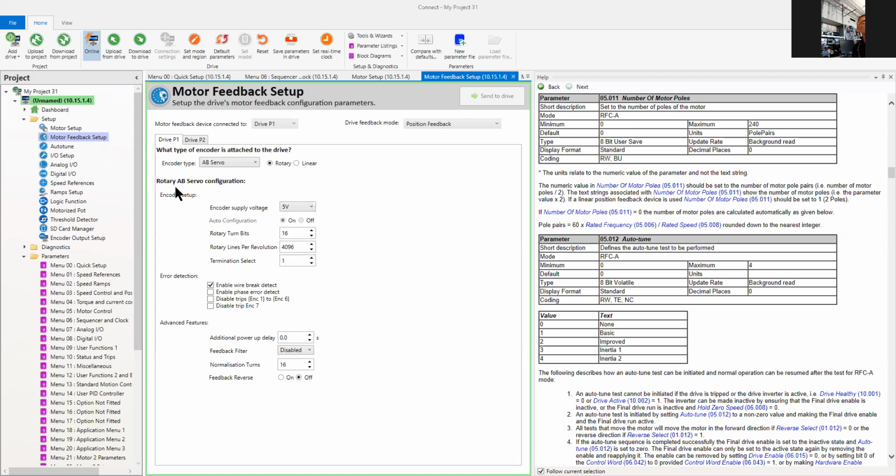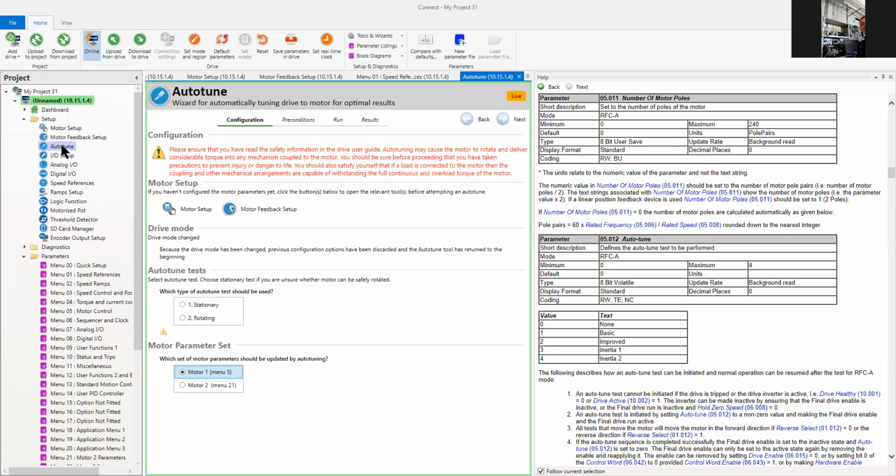Okay. Then you go to tuning. Let's apply, for safety reason, the key from here. So the power now is on, it's time for tuning. This auto tune is not a parameter; it's an extra piece of program in this VFD that you can go with, to find out these parameters.